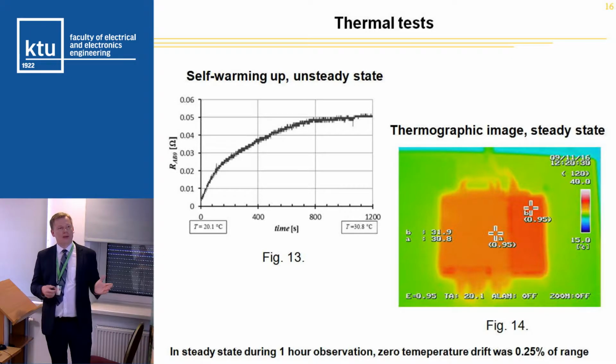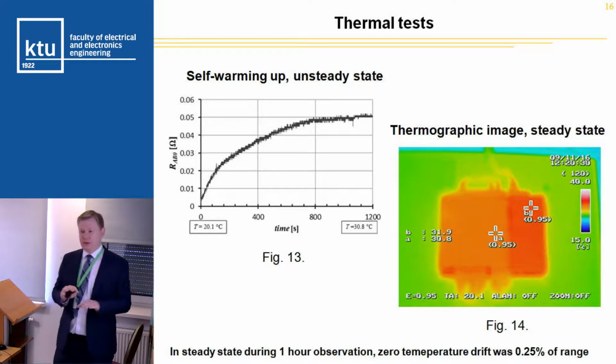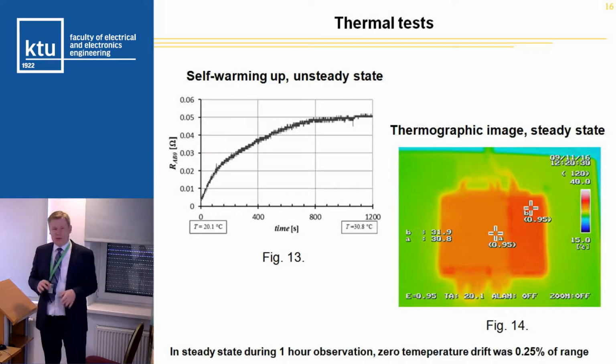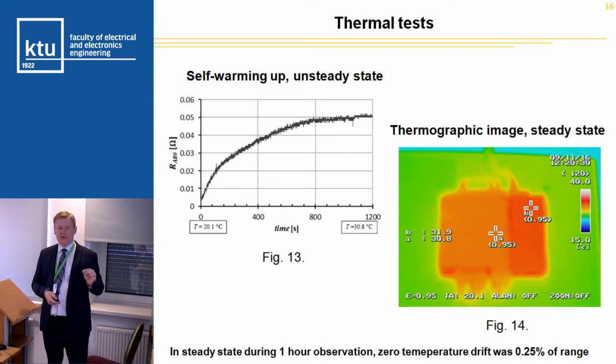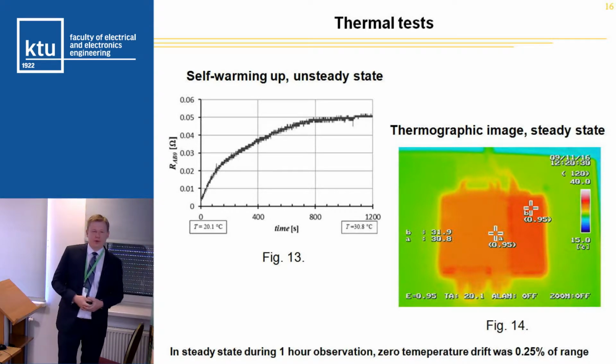So we need to wait 10 minutes for warming up, and then when the temperature is steady, we also measure drift, zero drift of the bridge, and this was quite good. It was 0.25% of range.